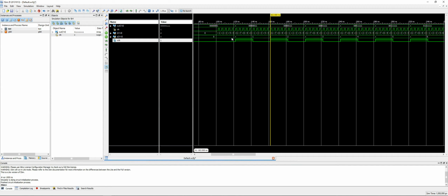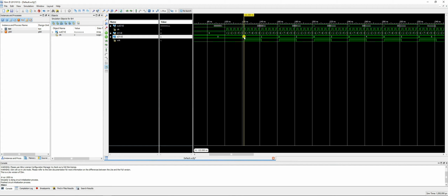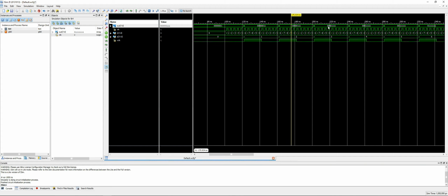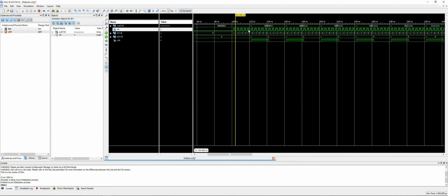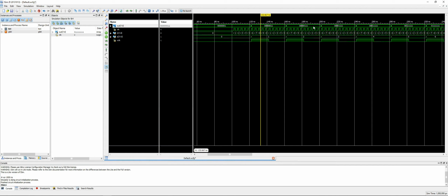You can see here, the A value is going to be calculated according to the positive edge. See this particular duration here, from here until here. So according to the slow clock, A only changes according to the slow clock. We have assigned A like a state, propagating from one state to another state, right? So the output also changes from one state to another state. So every state we can execute a different type of output, a different pattern of the output, right? This is the line for the clock. Clock here is the line for the slow clock, where A changes according to the slow clock now, no longer the clock. Then after that, you get the output pattern.